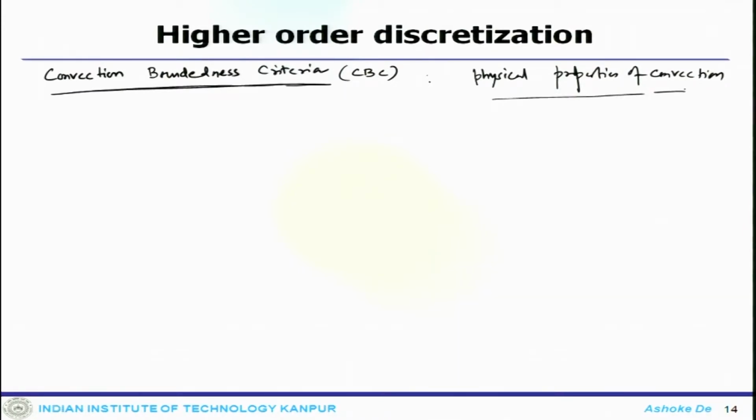Now, convection transports fluid properties from upstream to downstream. That is a standard process. If the gradient is in this direction, the flow moves in this direction. So, the numerical convection scheme should always be upwind biased, or else it will lack convection stability.